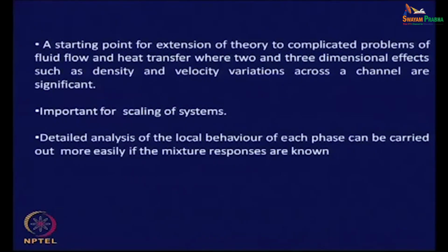So, in this particular case we have the mixture responses, since we know how the total mixture responds. Therefore, the detailed analysis of the local behavior of each phase can be carried out more easily. Due to its large amount of application coupled with its simplicity, the drift flux model is going to be very useful, and for most of the analysis of multiphase systems, a starting point is the drift flux model. It is not the homogeneous flow model.